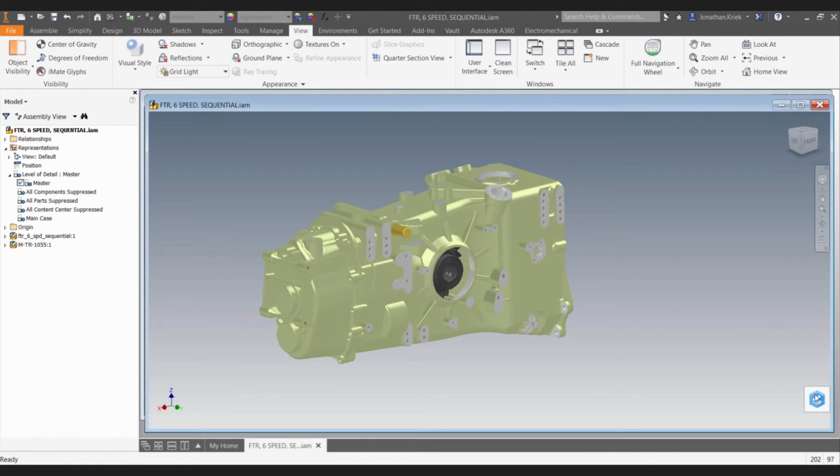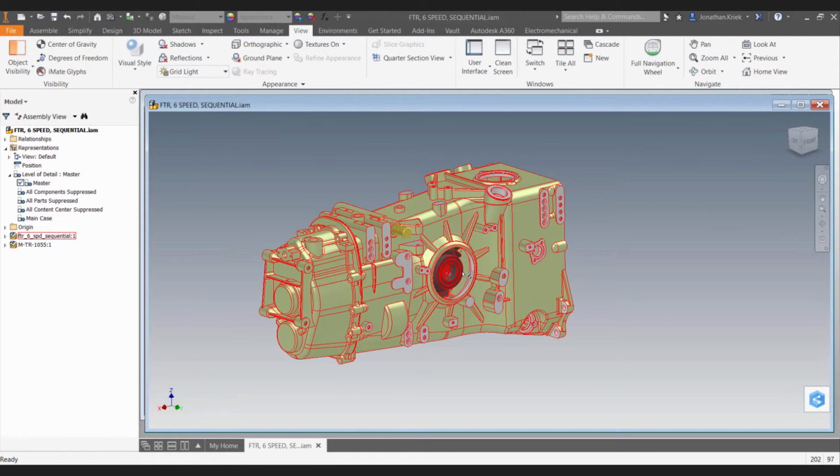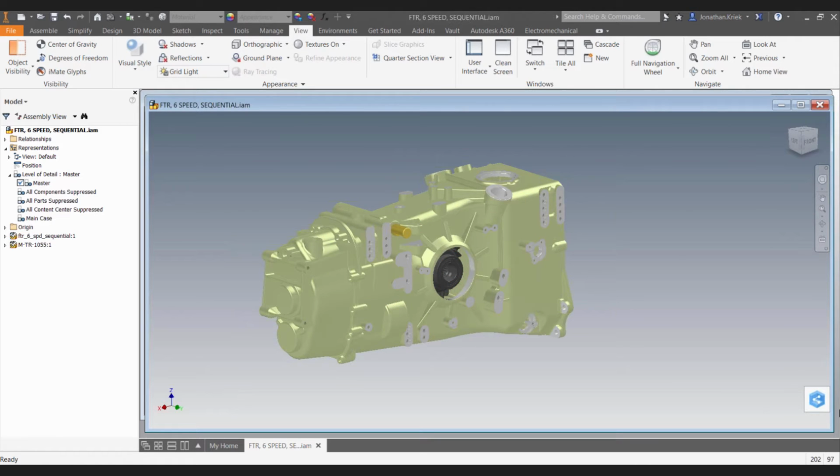If you don't see this icon in the bottom right-hand corner, sometimes people have come into Inventor, especially 17, and asked, what is this icon down here? Should I use it? What is it for? This is really the interface for connected design, and it works through A360 from there. If you don't see this icon, you can go into your view tab at the top panel. In your user interface, you'll see your common stuff like your view cube, navigation bar, and browser, and right down here is connected design on A360. If you don't see this, most likely Inventor wasn't installed correctly.